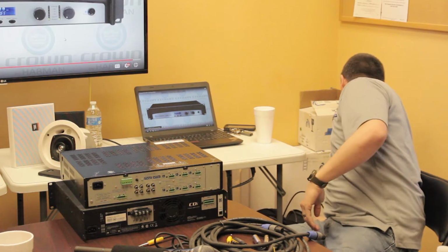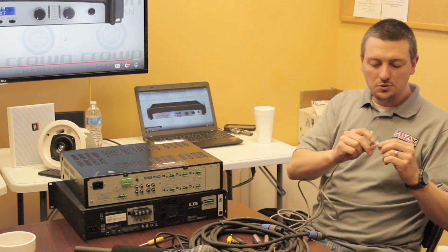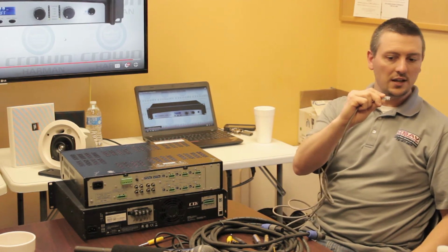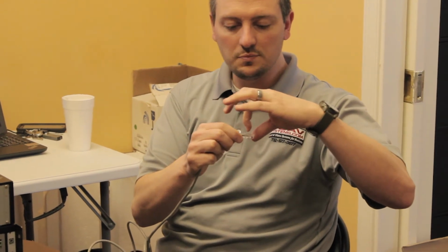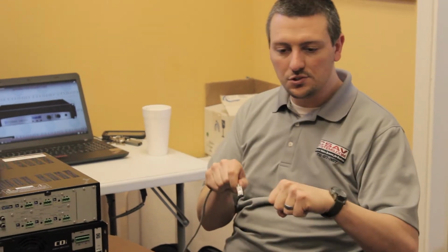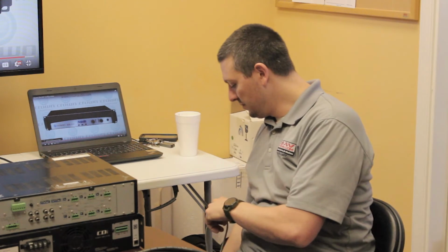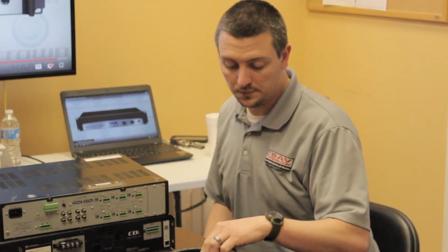A lot of times with these connectors, when you crimp them down, especially when you crimp down a lot of them, after you use your crimp tool, they stay pretty low like that. So you can plug it in, and unless you hear a click, it's not locked in. What you have to do is take it, bend it up a little bit like that, and it'll always lock and snap in. But you have to make sure when you're connecting something that you hear a snap. You can even pull it back to make sure. Otherwise, there's a good chance it's going to fall out, which I think was the case the other day, why the camera wasn't working.